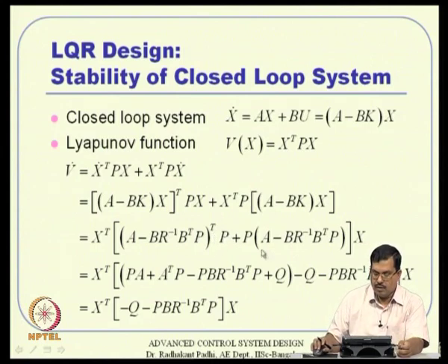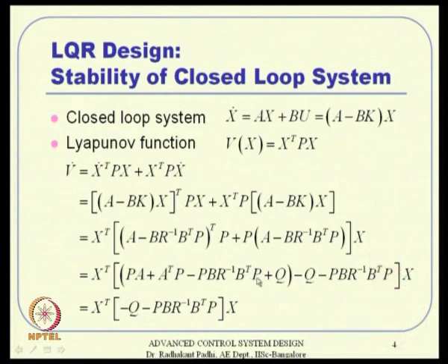We take advantage of all sorts of things while simplifying this, and then we add and subtract the Q matrix. The whole purpose of doing that is that one part of the expression turns out to be nothing but the algebraic Riccati equation on the left hand side. So, this is certainly equal to 0 on the optimal path, and this is gone, as long as we apply the optimal controller minus Kx, where K is R inverse B transpose P, and this equation is satisfied. So, this entire expression is going to 0. Once that is gone, we are left with only these last two terms.